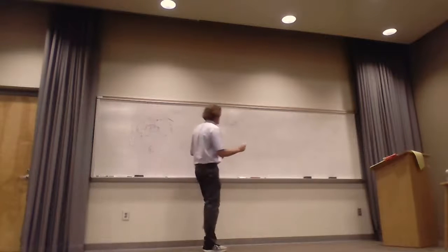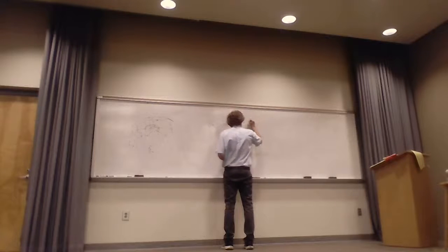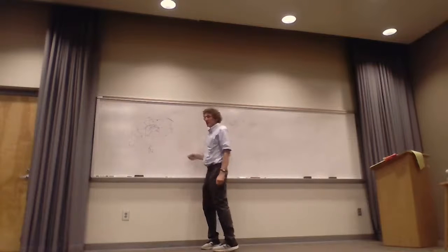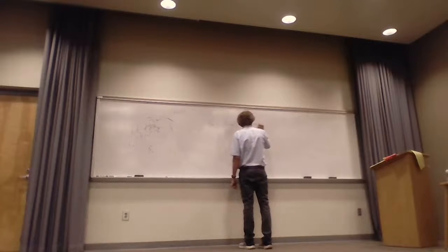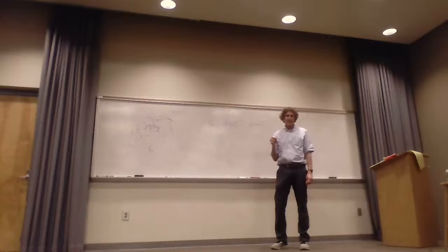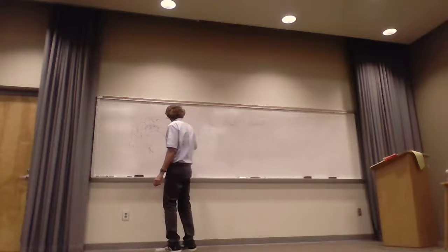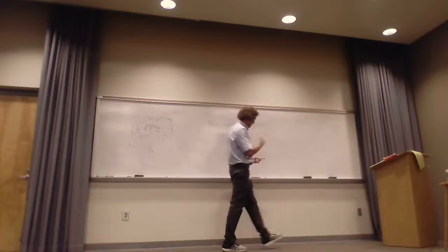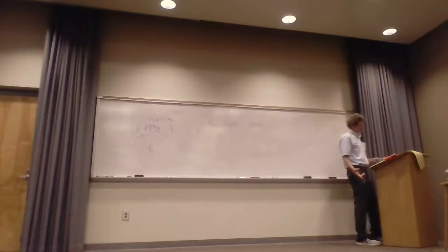Right? So there will be charge on this rim and opposite charge built on there, but not out here. So then that means the second resistance per meter would be 1 over the sigma of the outer conductor, and that would be 2 pi, what would the distance be that I use? 2 pi B, right? Now I'd use the radius of that outer part, 2 pi B times the skin depth, and that would be the resistance per meter, not 2 pi C. That's the point, okay? And that would be all that area right there that's flowing through, right? Just outside the rim. I'm giving away some answers, but I want to make sure everybody's clear on it.